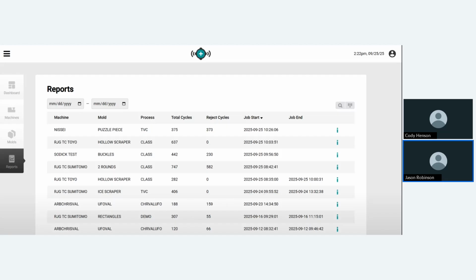Okay. Or another thing you can do with the warning is a three-way sorting. So imagine your parts fall out of your machine on a reversing conveyor. When it's a reject part, that conveyor reverses and goes backwards out the back of the machine in the red bucket. When it's good or suspect, it goes towards the front of the machine where you're standing. And at the end of that conveyor belt is a flipper chute. So now the warning, if it's a warning, it flips one way. And if it's a good part, it flips the other way.